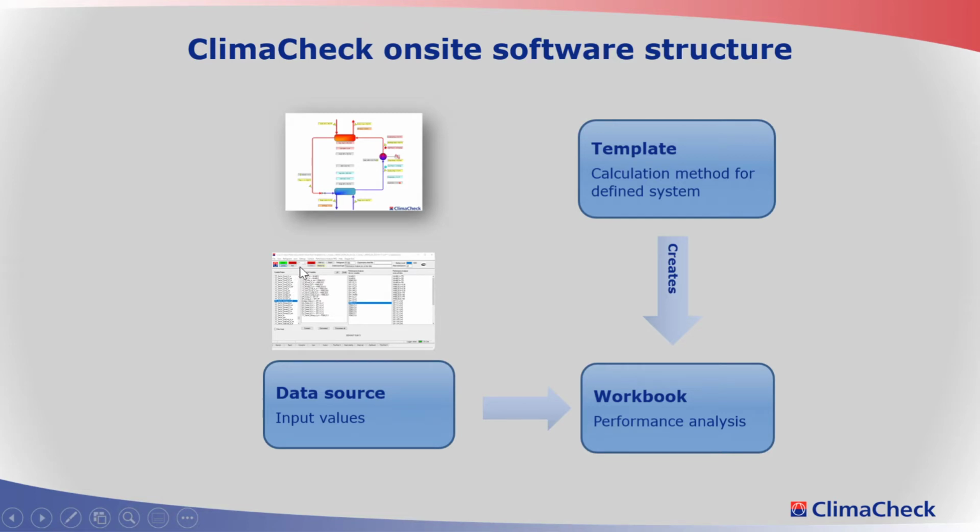If it's a two-circuit system, we will need to measure the two circuits. If it's an economizer, then we will need to measure the intermediate pressure, and we will have extra data. So we need to know what it is we're measuring and which points to measure.